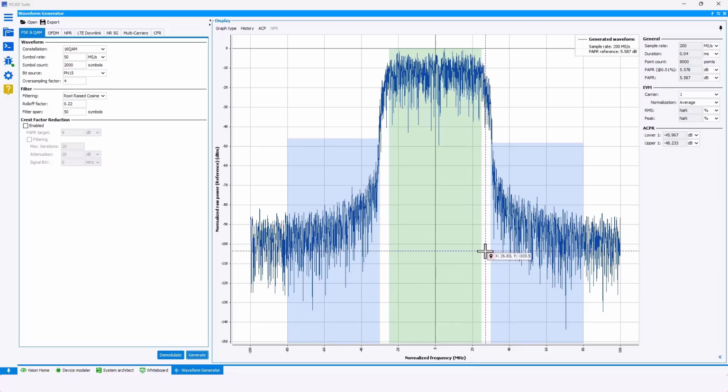Once the signal is generated, we'll review its general parameters, which will also appear in the AWG-IWF source. Additionally, we will note the PAPR value, which helps set the average power input to the source. It's important to ensure that the sum of the injected average power and the PAPR remains below the maximum power limit of the model.